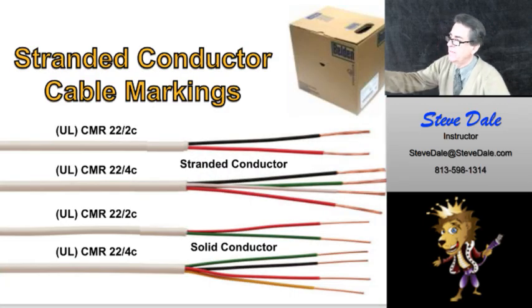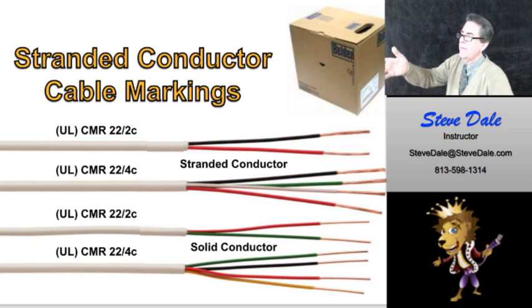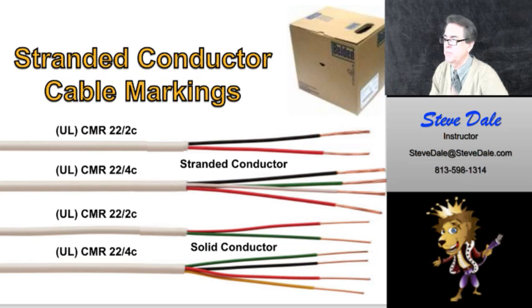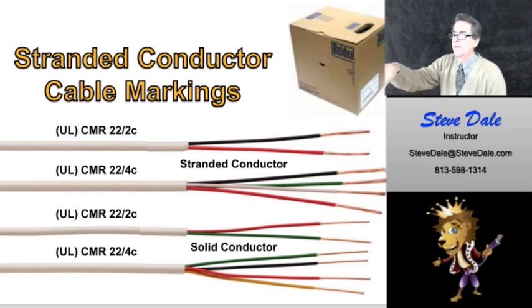Different kinds of stranded and solid conductor markings here. UL, Underwriters Laboratories, they mark conductors. CMR is communication riser cable. I'll explain that a little later. You can see an example here of some stranded conductors. Now this is not twisted pair. This is not conductors that are twisted to reduce crosstalk. This is just the actual metallic strands being twisted.